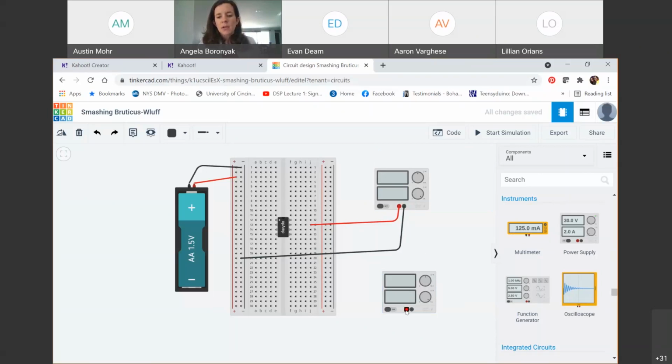You have to make it positive 15, which again means the red terminal is 15 volts higher than the black terminal. If I really need something to be negative 15 volts, then I'm going to attach my negative terminal into this row. That's my negative power, because it's negative 15 volts compared to the red. So that means I want the red to be my comparison point where I'm comparing all my voltages against. So I'm going to wire it back to my ground.